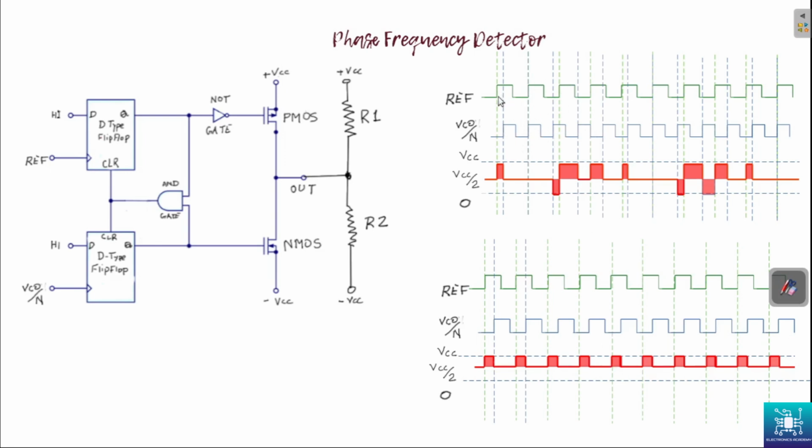We'll come to that. So here also, when this signal goes up first, the output goes up and the second signal brings it down. One thing we see is that when the second signal is leading the first signal, at this point, instead of the output going up, the output goes down, and the rising edge of the second signal again brings the value back to 0. It's all done by this circuit.